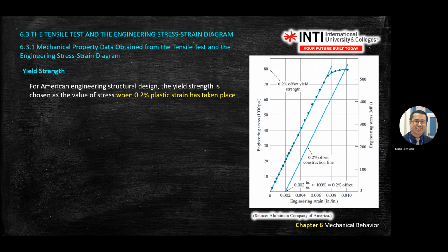This one you find the value already, but you rework the equation by considering 0.2% to here, to here. So you can see it is the same thing. Your stress will be the same, but what is moving? Your strain value is moving by 0.2%.